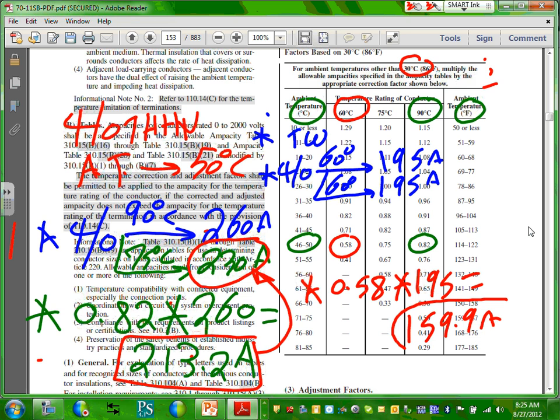159.9 amps. The same size conductor can carry 213 or 159, or like 160. Do you see why we use the 90-degree column? Can I have a thumbs up? We got it. See the power of using an insulation like that; you don't want to use THW.